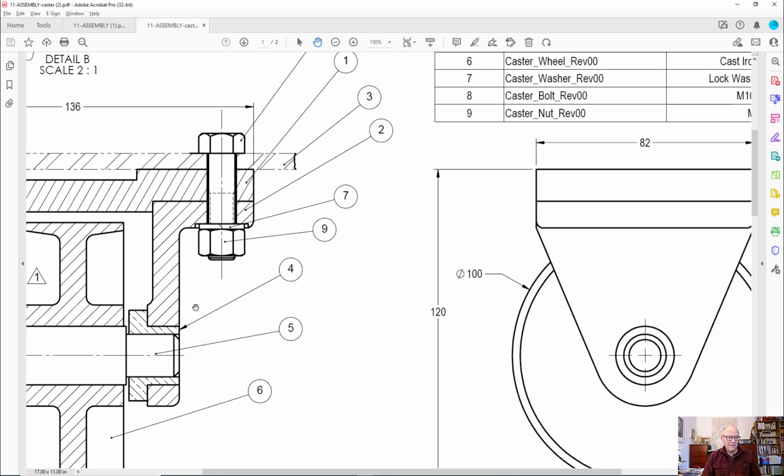Over here, it'd be from the bottom of that surface down to here. So I just offset a line down 48 so I could see where that hole was. Now I'm going to bring it through, and then I want to see, well, how big is that hole? When I look at the sides of that hole, I'm just going to take half of it and offset in either direction to indicate where that hole is. I've also got 2 millimeters thicker down here, so right now it's 10 on here, but the raised boss is going to increase that to 12.